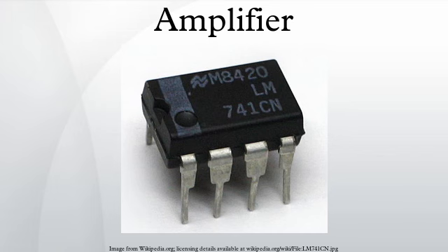This arrangement gives excellent efficiency, but can suffer from the drawback that there is a small mismatch in the crossover region at the joins between the two halves of the signal, as one output device has to take over supplying power exactly as the other finishes. This is called crossover distortion.